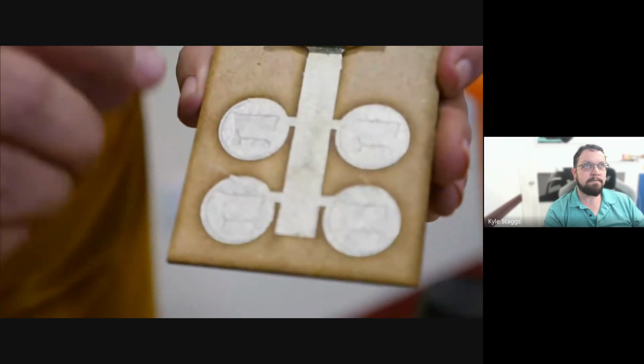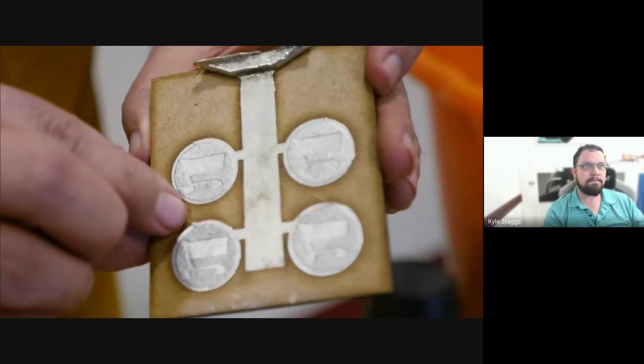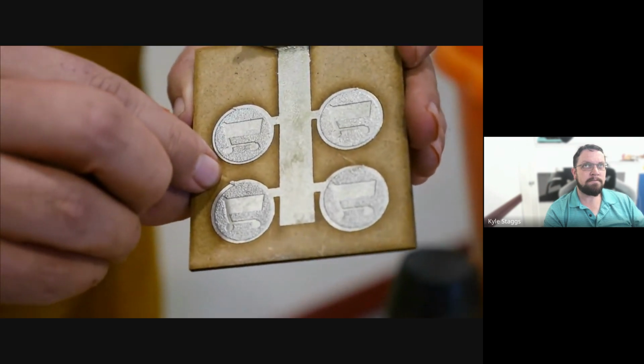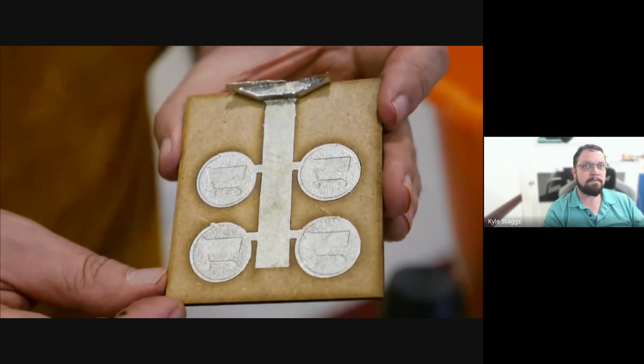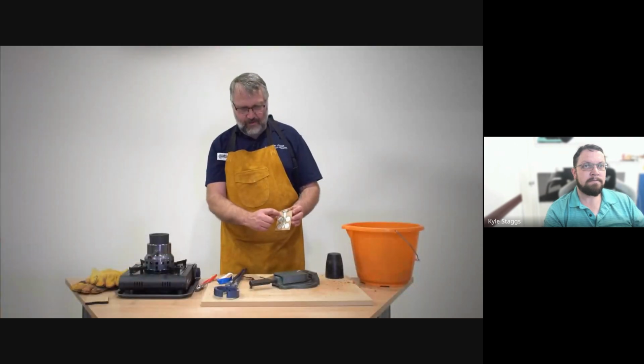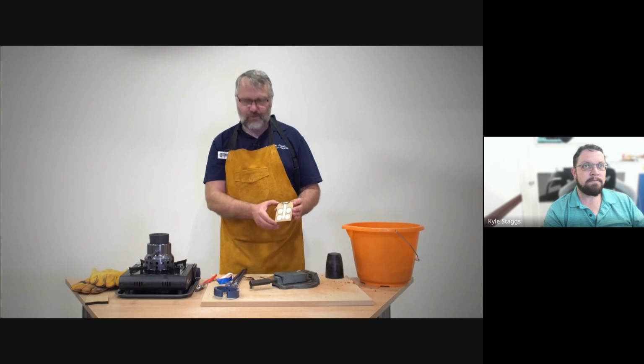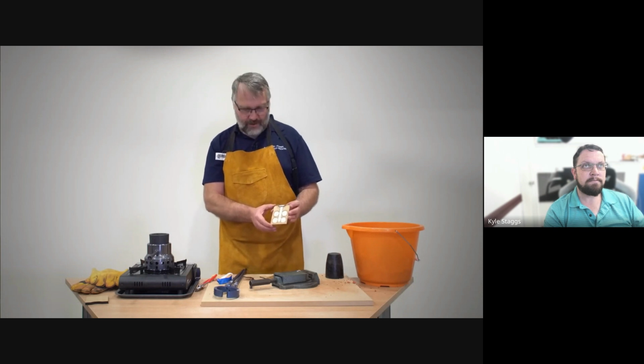Where the air vents ran, you can just see a very small amount of metal just started to go up, but there's no problem with that on this product. It's just a simple matter of breaking them off the main feed, and then a quick touch with the file or a bit of emery cloth will give it the finish that we're looking for.